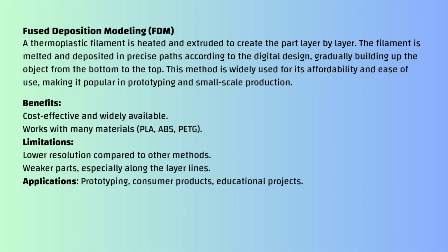Fused deposition modeling, or FDM, is one of the most accessible and widely used 3D printing technologies. It operates by feeding a thermoplastic filament like PLA, ABS, or PETG into a heated nozzle. This filament melts and is deposited in layers along a predefined path. The nozzle moves in the X and Y axis while the build platform moves vertically, building up the object layer by layer.